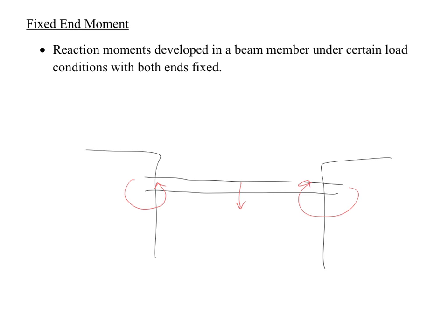It's like an anti-torque. Think about torque. If you apply force in the middle of the bridge, it's going to apply torque, which would cause the actual member to bend down like this, and it would want to snap. Well, the ends of this, they rotate the other way, or they apply a moment in the other direction. So when these are fixed in the wall, you draw moments in the opposite direction that torque will cause it to rotate. If you're not sure what I'm saying right now, maybe cut the bridge in half. You put a force here, which way would this half of the bridge go? Clockwise or counterclockwise? Clockwise. It would rotate like this, right? If you apply force right here, it would rotate like that, right?